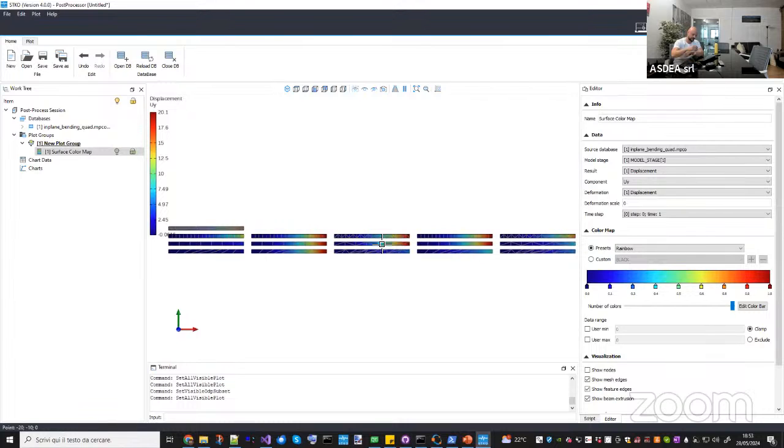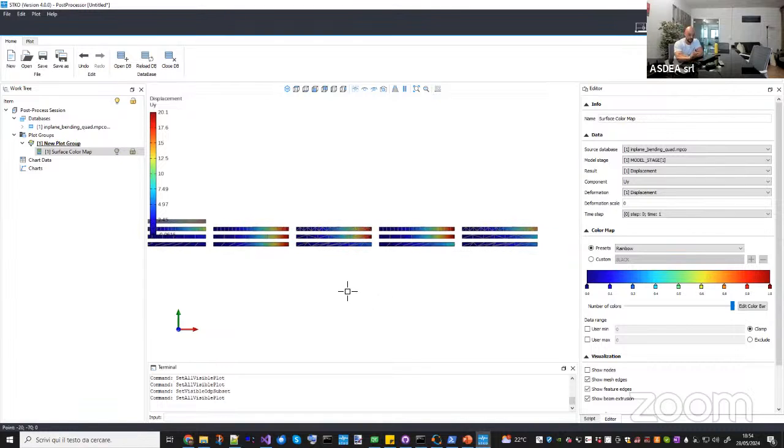Okay, so we have another couple of minutes. I just want to introduce also a little bit of nonlinear kinematics, which is the third reason why we decided to implement these new elements. But then I will talk about the nonlinearity in a next webinar. So the other reason why we decided to implement this element is that all of the shell elements in OpenSees didn't have a proper treatment of large rotations. Handling large rotation is a mess in computational codes.